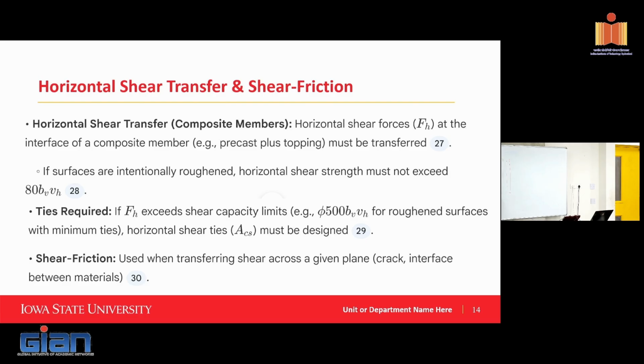The end regions of the concrete, I'm looking at something on the order of 6 millimeters, a very thin layer here. They don't tend to get a lot of aggregates, because when you vibrate it, you push the smaller particles towards this. So if you're connecting this with another region, and even if you put epoxy here, and here's your second panel coming in, this region is still weak. So if you prevent crack opening here, the next likely place where a crack develops is just adjacent to it, because it doesn't have any aggregate, so it's easy to crack.